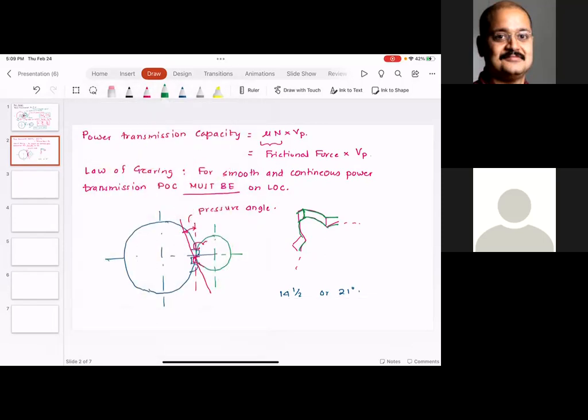and I have this small gear. And I'm going to cut rectangular teeth. So no weird shape, no curvature, pure rectangular teeth. Now my question to you is, if I have two rectangular teeth, one on the pinion and one on the gear, come in contact, would there be any power transmission, or would they lock? Can you visualize that they would just lock?